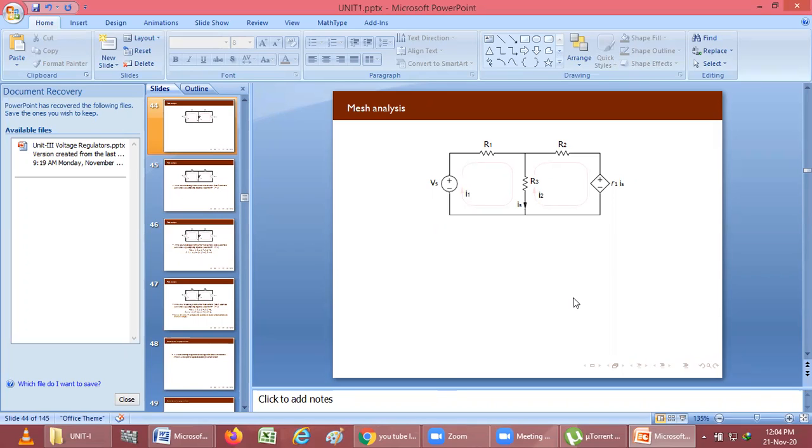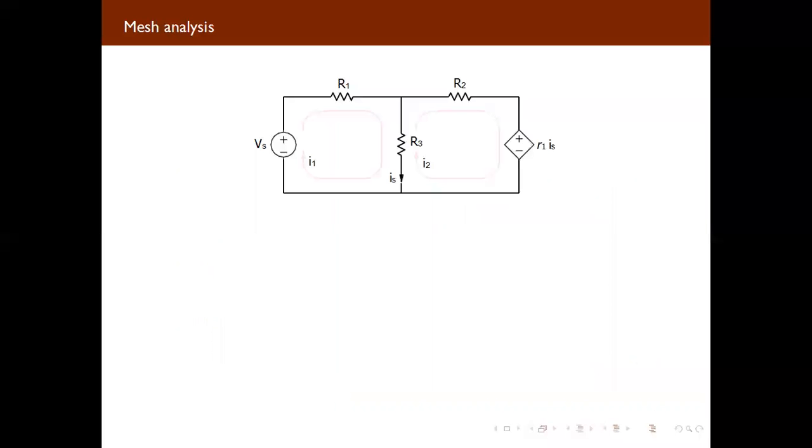So here, if we have a network which consists of many energy sources and impedances, you can see here we have two voltage sources and three resistances. If in any given network with many energy sources and impedances KVL and KCL are not enough to analyze the circuit, we can use the mesh analysis method to find the value of unknown current.